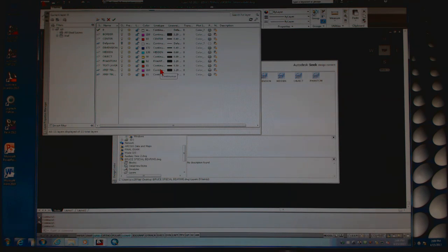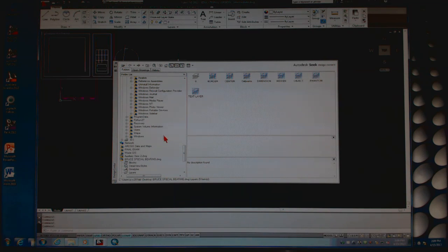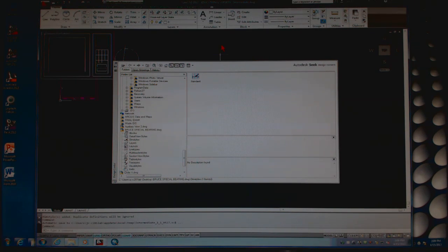So this is another thing we do. We'll set up a template drawing that has all the layers, dimension styles that we want and all that. So when we start a new drawing, we either open that drawing and automatically has everything in there, or we'll just start a new drawing and drag it from the Design Center into there. So you can see how the Design Center works. And I'm sure y'all probably saying, well, dang it, I could have used that a long time ago. With the dim stuff. And like I said, this one would have worked the same. If this one would have had a dimension style, I could drag it, bring it over in there, and it'll automatically put it in there for you.